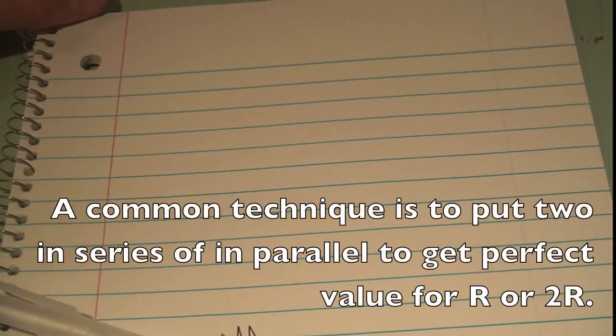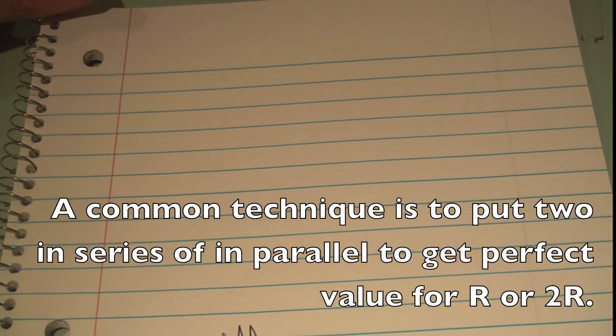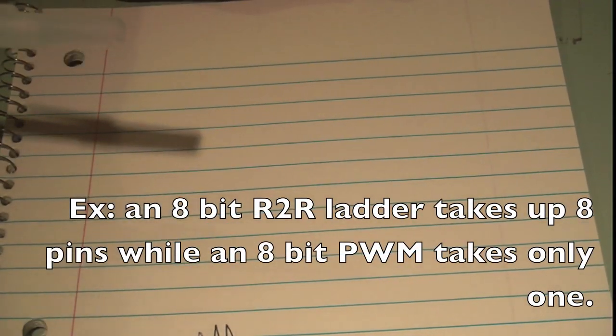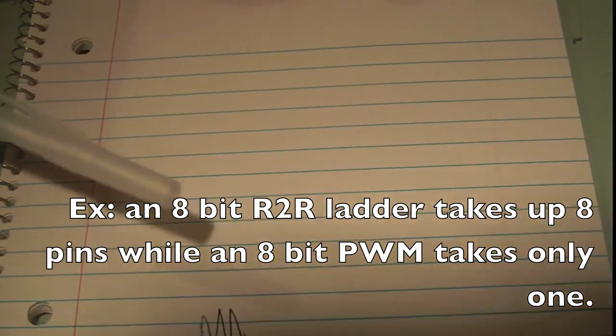Obviously, resistors are cheap, but there's also no perfect halves in the E12 range. The closest things you have to a half are like 2.2 and 1, or 8.2 and 4.7, or 8.2 and 3.9, so your values aren't going to be exact because of that. And it takes up too many data lines on your microcontroller. So for that reason, I chose PWM and a low-pass filter.